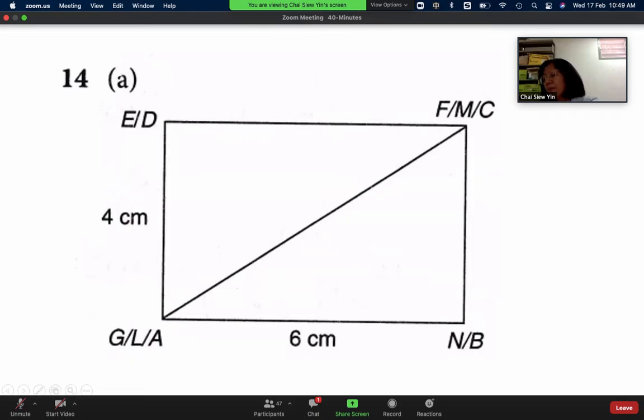I think I need to go through one more. Do not ask for graph paper. You can only draw the answer on the space provided. Yeah, the reason why graph paper is not given is very easy. You just draw a line and then straight away you can draw the perpendicular line without measuring. Now, since it is on plain paper, ladies and gentlemen, to draw a straight line, we must always start at the bottom. Use your compass. The best way, the most accurate way, use your compass.